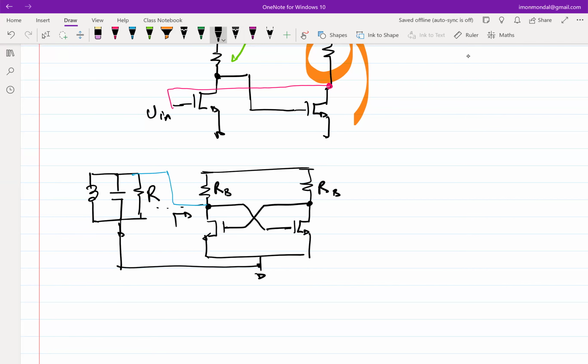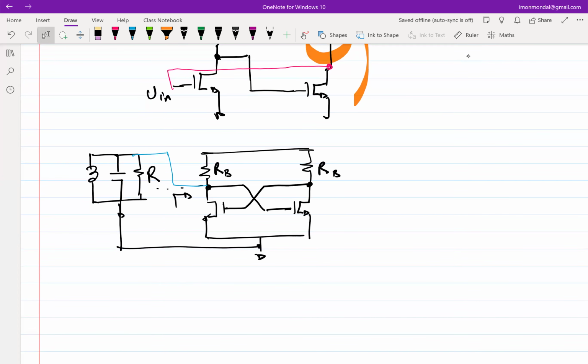So ultimately, if you have to use such a circuit, you'll have to also take care of biasing, right? So, how do I take care of biasing in this way? Now, if you think about it, this is a small signal ground. And the whole reason we put the RB is because we wanted to ensure that the transistors are in saturation and all those good things, right? Because ultimately the common source amplifier configuration requires the transistor in saturation, a certain amount of VDS and so on.